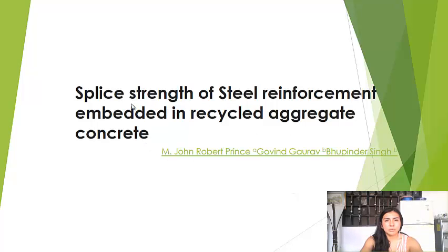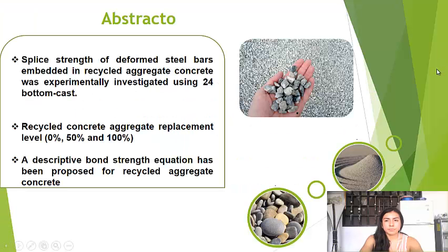I will be talking about a study of splice strength of steel reinforcement embedded in recycled aggregate concrete. For this investigation, 24 splice beams with steel reinforcement were used, and the levels of replacement of aggregate with recycled concrete material were 50% and 100%. Other variables investigated were concrete grade, normal and high strength. Finally, a descriptive equation for recycled aggregate concrete has been proposed.